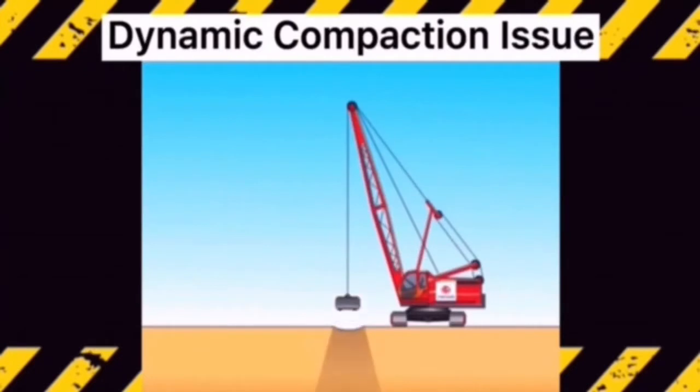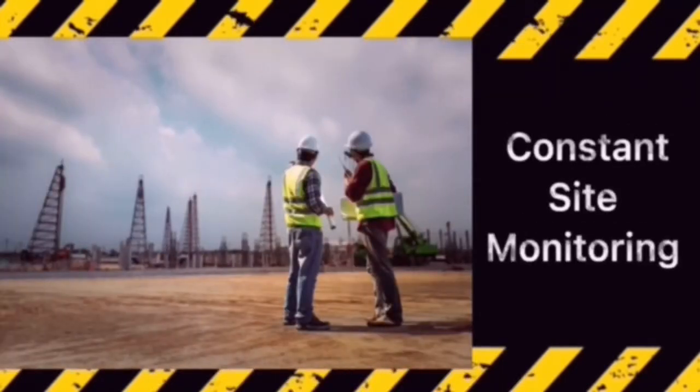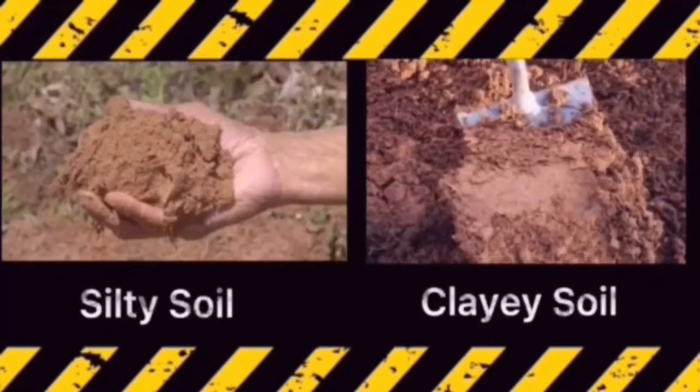And for the dynamic compaction issue, constant monitoring is required to check for the formation of craters, ground heave, ground vibration, induced settlement, and pore pressure development during the operation of this method on the site. But this method becomes more complicated in silty and clayey deposits below the groundwater due to their relatively low permeability.